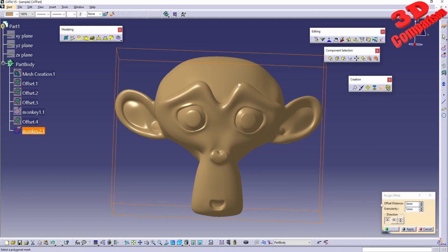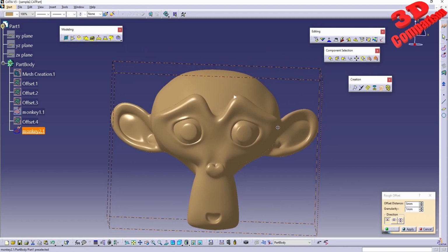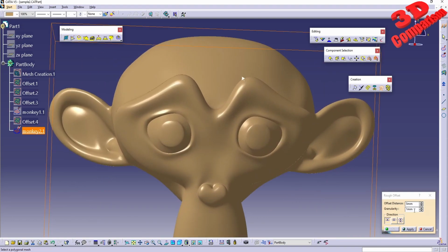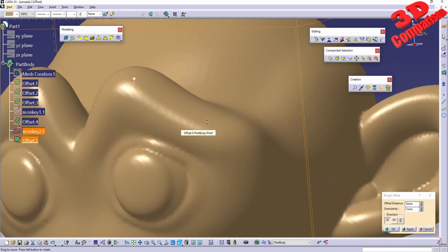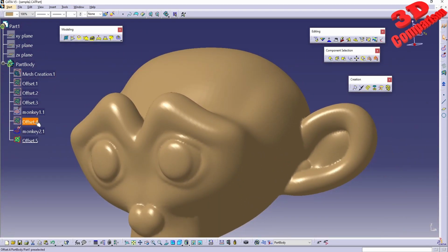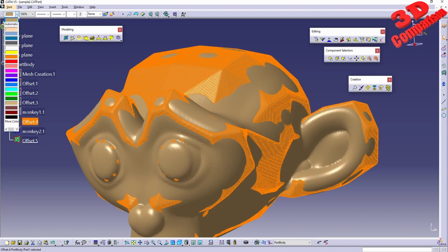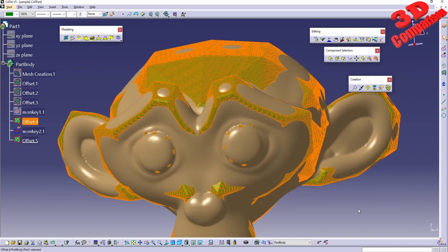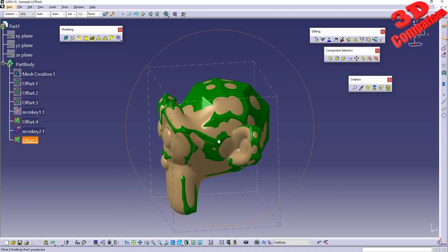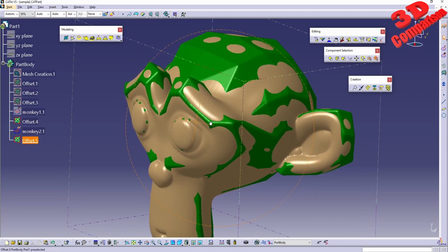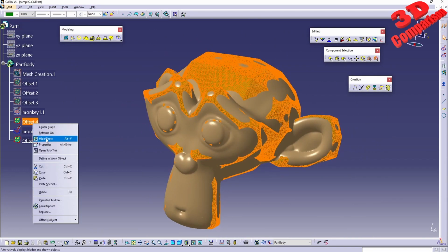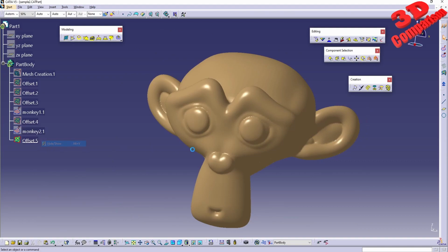And if I have this offset, for example, at 5, keeping the granulation set to 1, this will still be converted, and we'll have some rougher edges, but not as much as the previous one. So we have this offset. I'm just going to change the color so that we can better visualize it. And we see the green one will be a lot rougher, but if we subdivide it before we import it in CATIA, we can obtain better results.